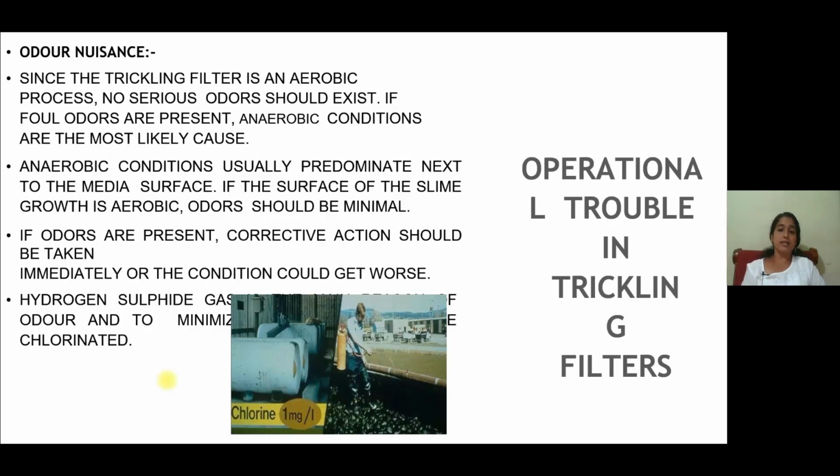Then odor nuisance. If the aerobic action does not take place in the filter media, then the odor nuisance will happen. That is due to the anaerobic decomposition.